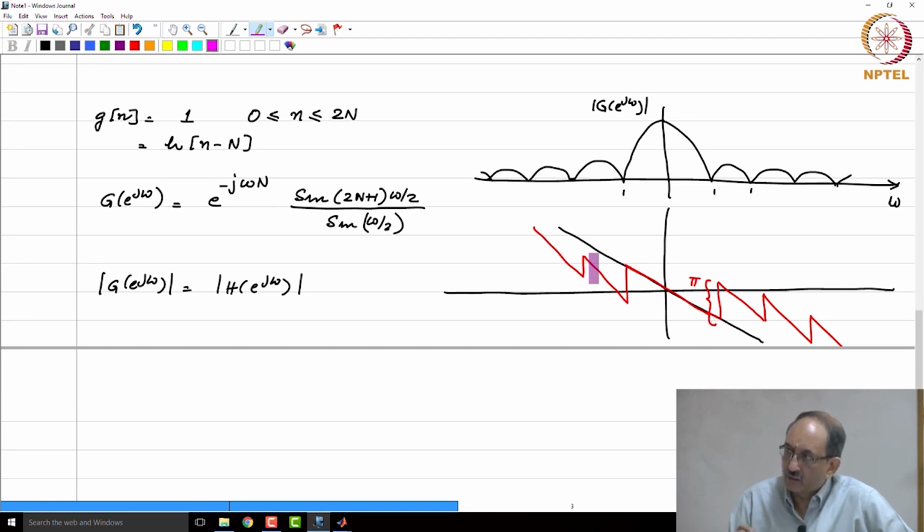The frequency can be anything, but as far as the signal is concerned, you replace frequency by frequency mod pi because the resulting signal is no different. But when you are looking at the phase response, it is precisely given by this term, which is minus omega n, and minus omega n is exactly this. There are no issues here, but we are going to the point that you have in mind in a minute.